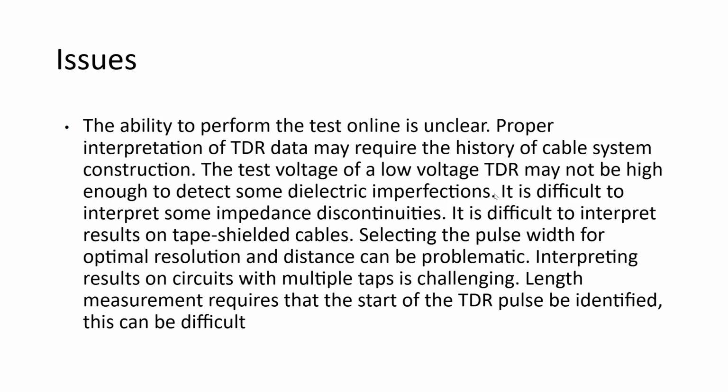What is normally done is we make the high impedance fault a short circuit. There is no other option actually. All cable companies do it like that. If there is a high impedance fault, they will make it a low impedance fault, which means they will damage the cable further.